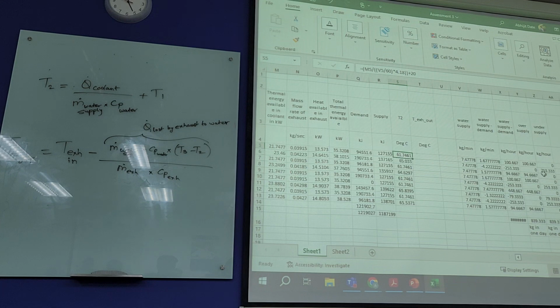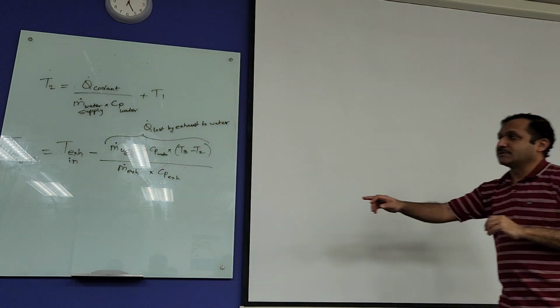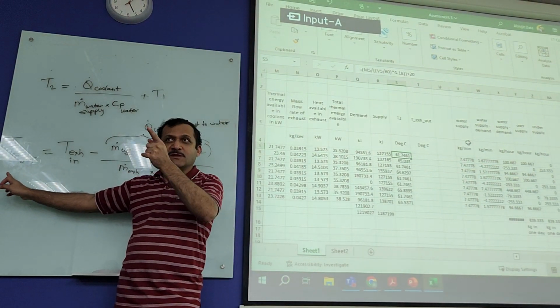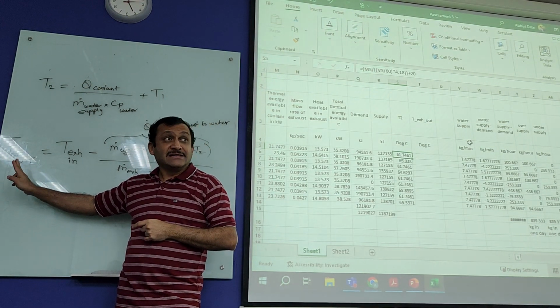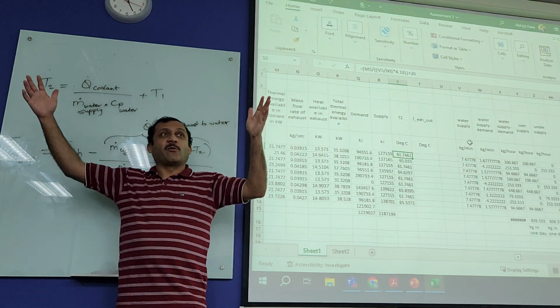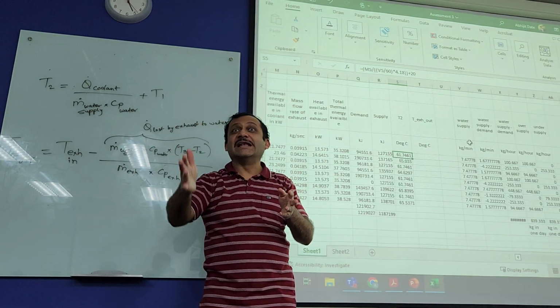Oh yeah, okay. This is flow rate. Flow rate divided by density is volume. Then, if you're getting your T exhaust, that temperature, negative values, because we found one of your classmates made a silly mistake. I would share that with others so they won't make the same mistake. If you're getting a negative value, definitely you're missing 1 kW from the original table when you added the total electrical power.